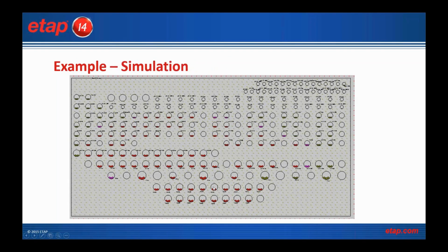As far as the limitation inside the program is concerned, there's no significant limitation except the ones that are determined by the Neher-McGrath or the IEC 60287 method. Usually the limitation is just on the dimension, or the ratio of the dimensions of the raceway.